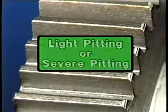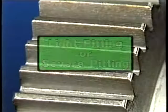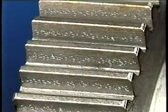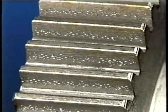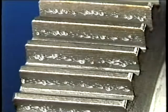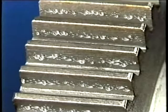Pitting may appear as either what's called light pitting or severe pitting on a gear's tooth. Light pitting appears as very fine holes or cracks in the face of a gear. Light pitting can be expected in a gear set as the gears age. Severe pitting appears as large holes in the surface of a gear's teeth, and severe pitting will eventually cause the teeth to break.